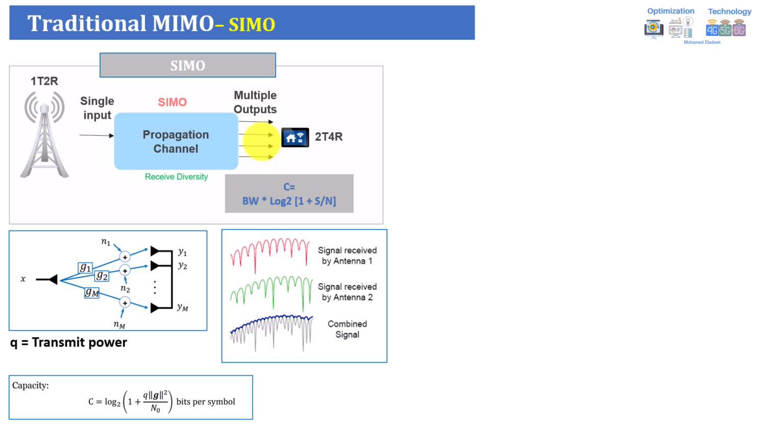For example, you have four receivers, so it will receive the signal from its four receivers and select the one with the highest quality, the best antenna of the four with the strongest CNR. This means you will use only one antenna at a time. It evaluates which one received the signal in better quality and uses that. So the first one is called selection combining.